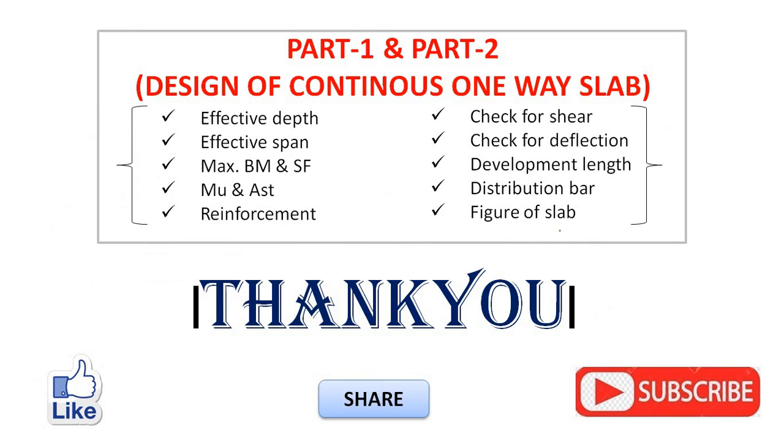So here we complete the whole design of the continuous one-way slab, which we have seen starting from effective depth, then effective span, then maximum bending moment and shear force, then MU and AST, then reinforcement, check for shear, check for deflection, development length, distribution bar, and figure for slab.